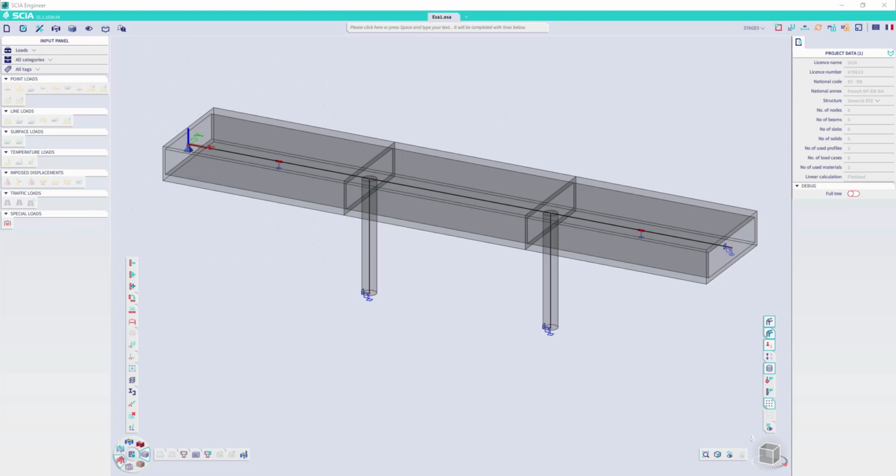Of course, with nonlinear construction stages, as the word says, you can take into account nonlinearities in the model, but mostly nonlinear construction stages allow you to take into account the history of deformation on the structure. What I mean, I will show you with a simple sketch in Paint.